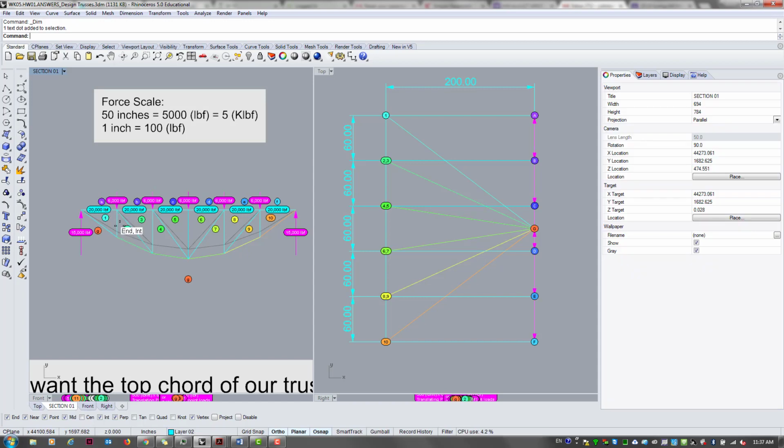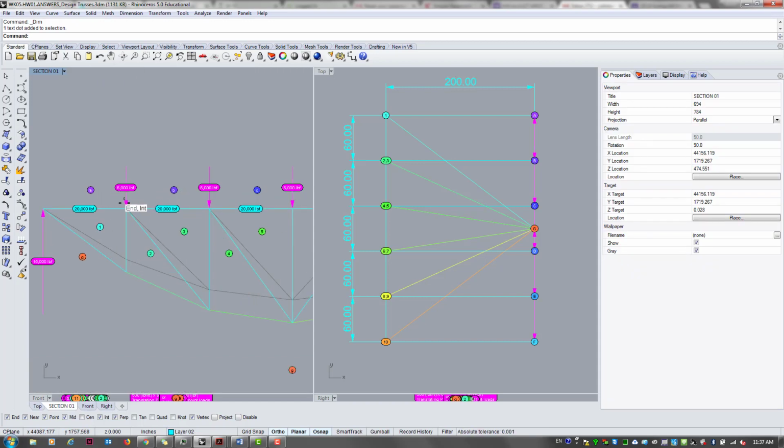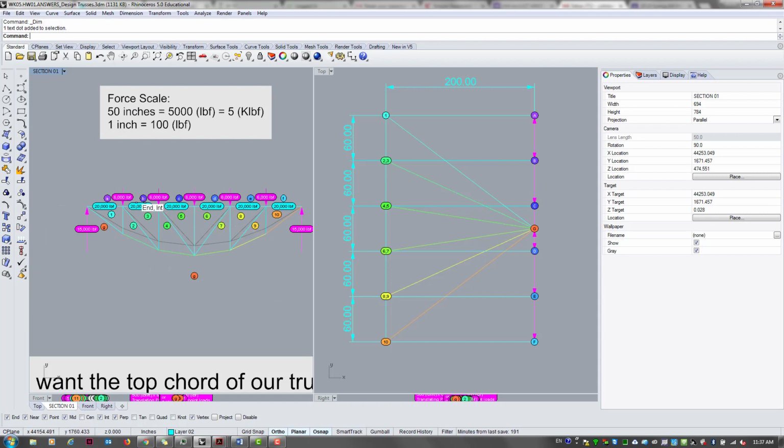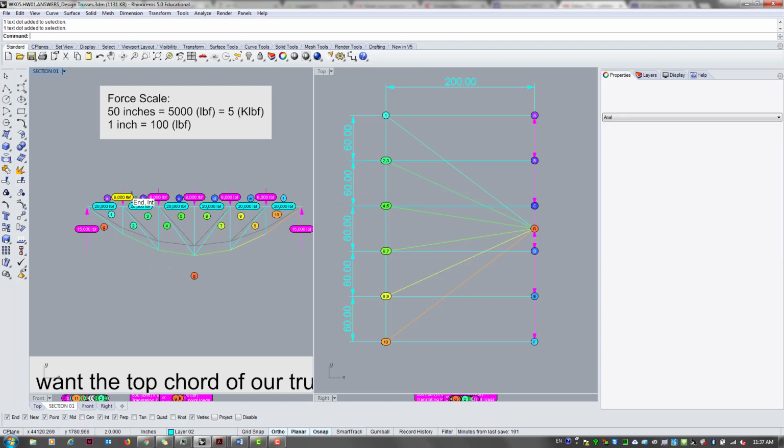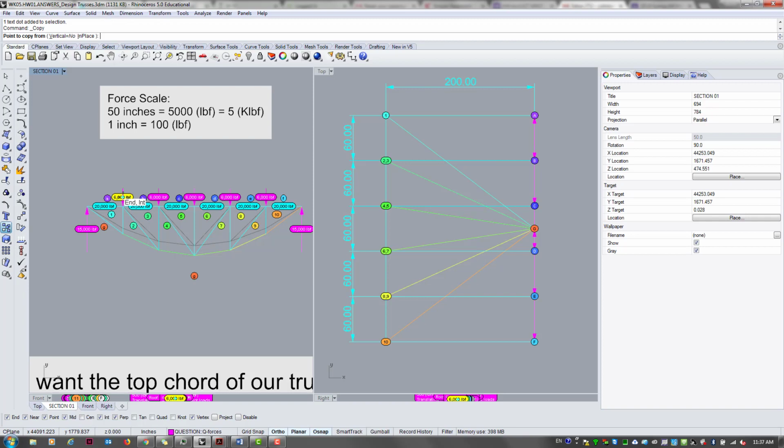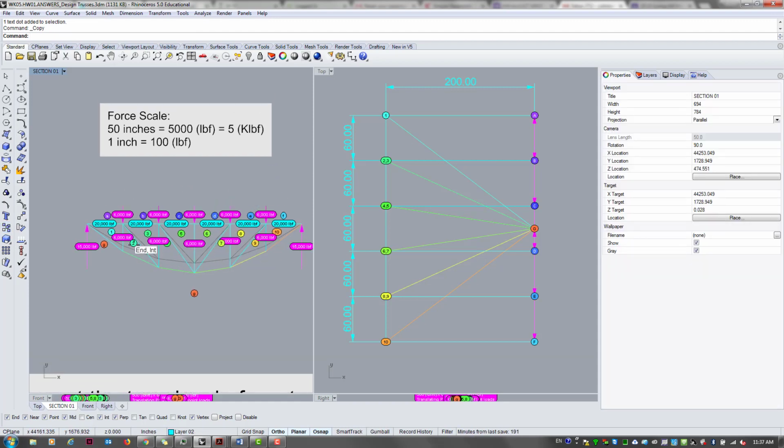determine whether it's tension or compression, you can, for example, look at that, but it's probably compression, right? Like you can look at this point, it's 2 1. 2 1 is upward arrow, so the internal force at this point is pointing up, so it's in compression. So all of these vertical ones are in compression. And the interesting thing is it's exactly the same magnitude as the applied force. So all of these vertical force is pretty much going down directly to the bottom chord.